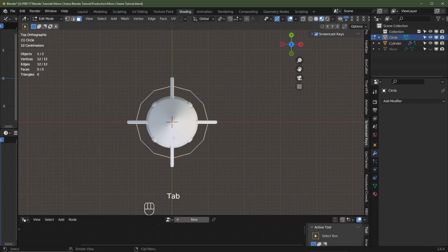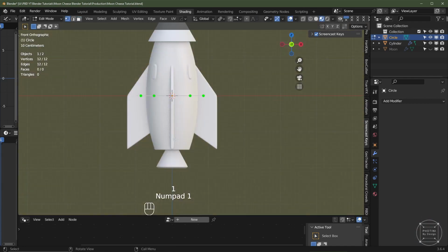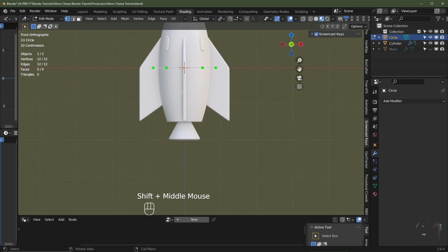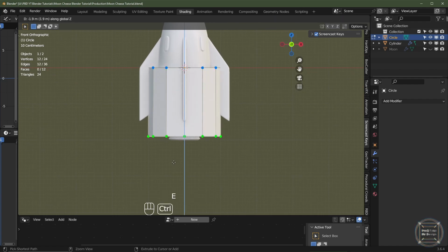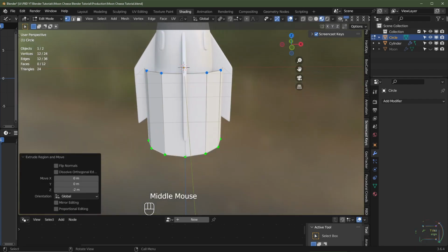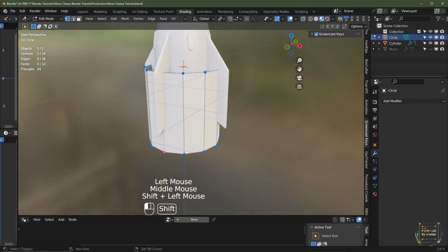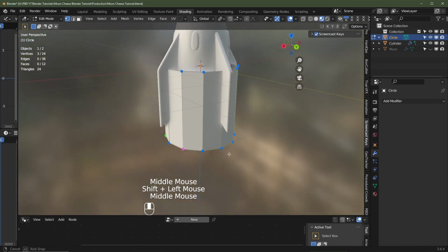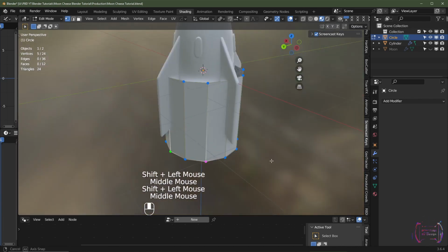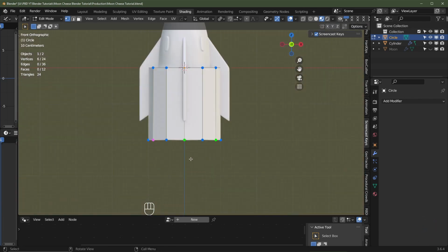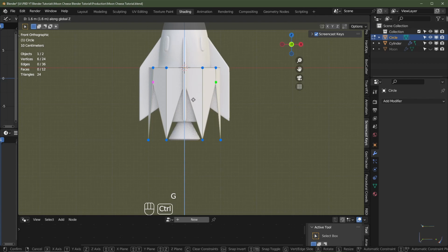We'll go to vertices select mode, so that's number 1. I'll go into front view, and I'm going to drag this down, so hit E, Z, we'll drag it down to round about there. Okay, every other single vertice, we're going to select these. So I'm just shift left click selecting, and then I'm going to hit G, Z, and we'll just drag these up to around about there.